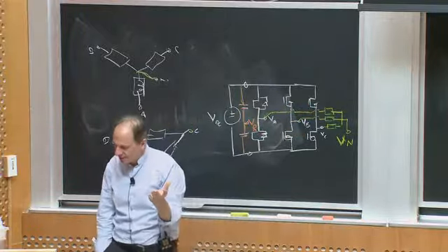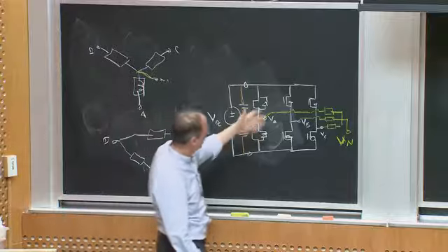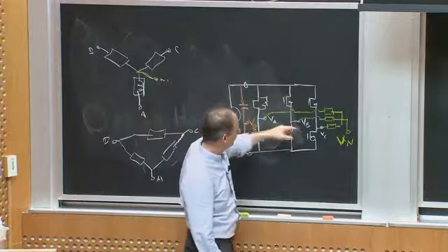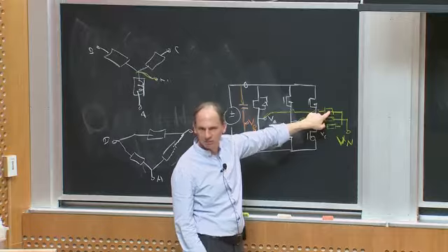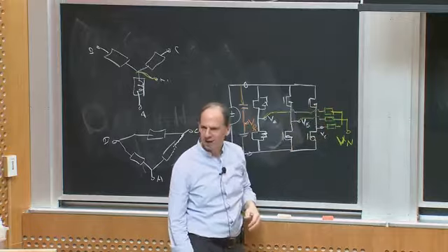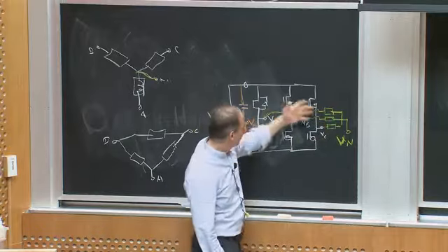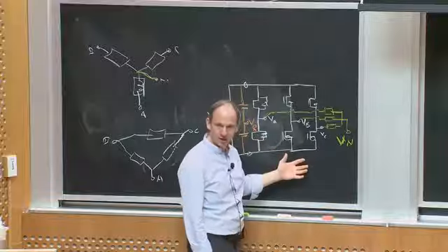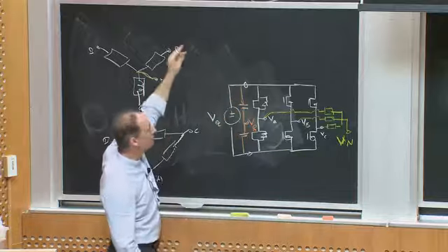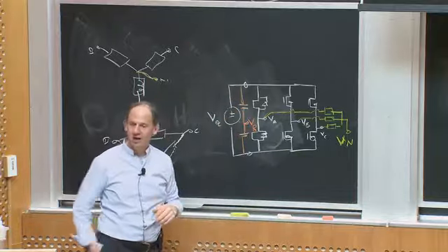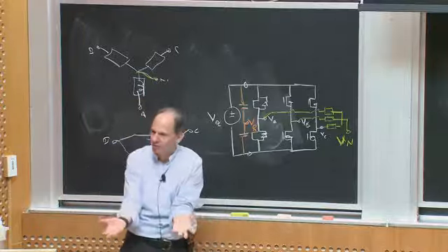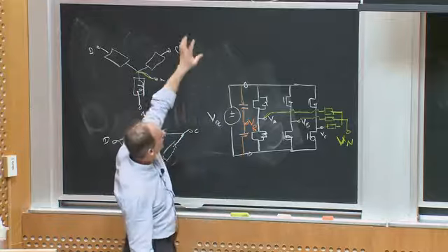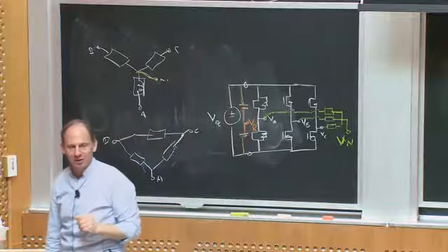Where's the exception to that? It turns out that if I wanted to generate a certain ripple in an inductive load like a motor, inductive back EMF kind of load, you end up having to switch this bridge at a higher frequency than you do the 3 sets of single phase. So in a system where it's a really high frequency output and your switching losses are heavily dominated, the top solution actually ends up starting to be advantageous.